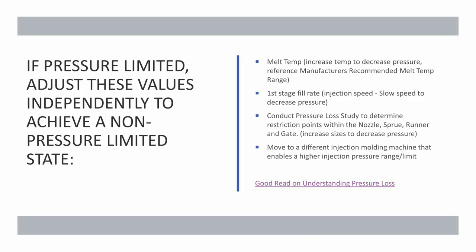First stage fill rate, your injection speed. If you slow your speed down, you're typically going to reduce your pressure as well. Again, if you're changing your first stage speed, I would still recommend taking pack and hold off to confirm where that first stage fill truly is from a volume perspective.